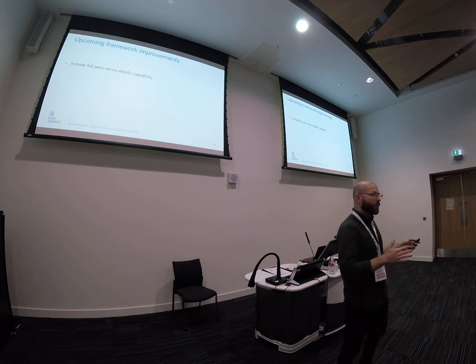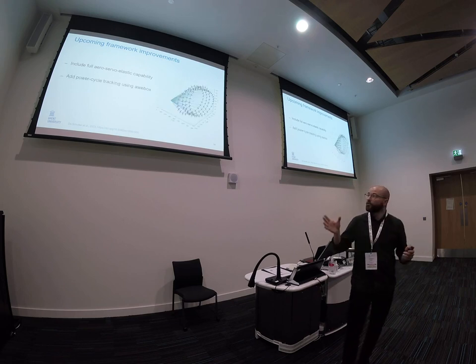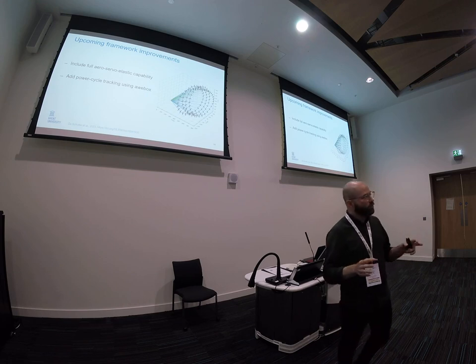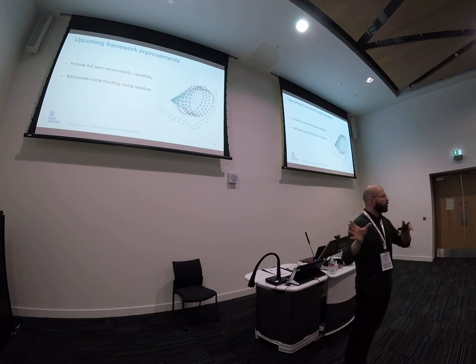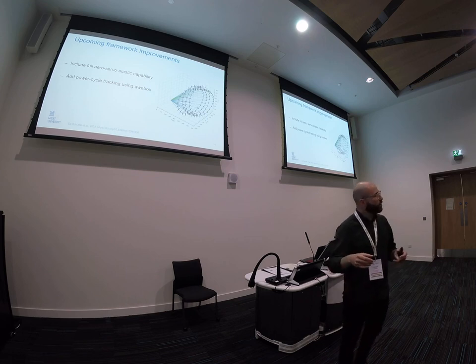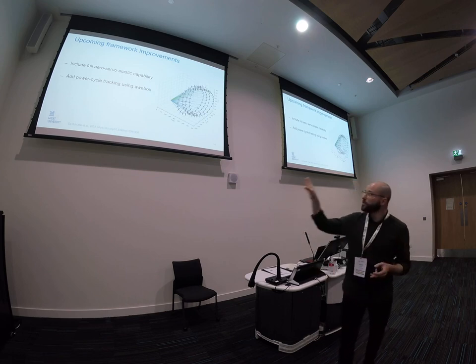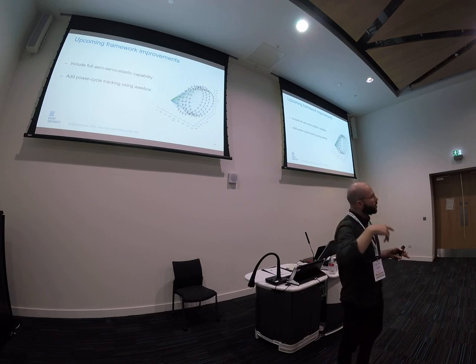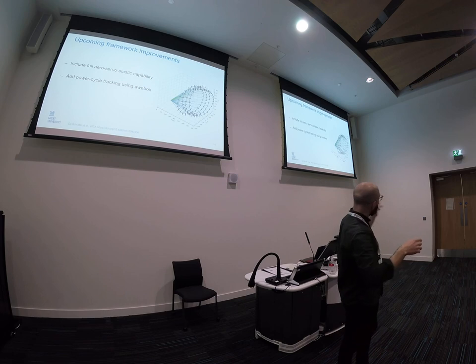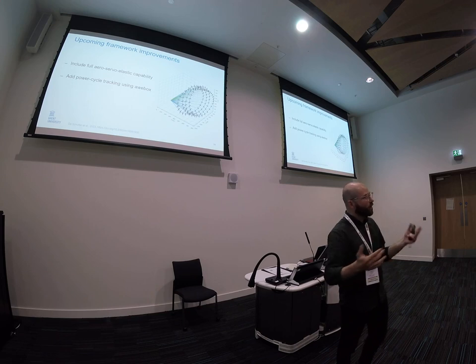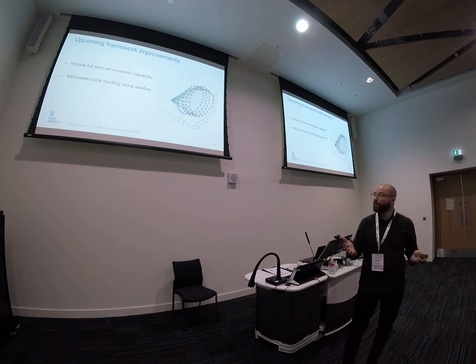So the first step would be to add the inclusion of a full trajectory. So what we want to do, we want to couple our framework with the toolbox, which generates the full trajectory that the kite would fly. So what you can see on this trajectory, for instance, is the kite that is flying 4 loops in power generation in blue, and then you see the green part is the retraction phase of the kite, so this typical pumping mode behavior that the kite might fly.